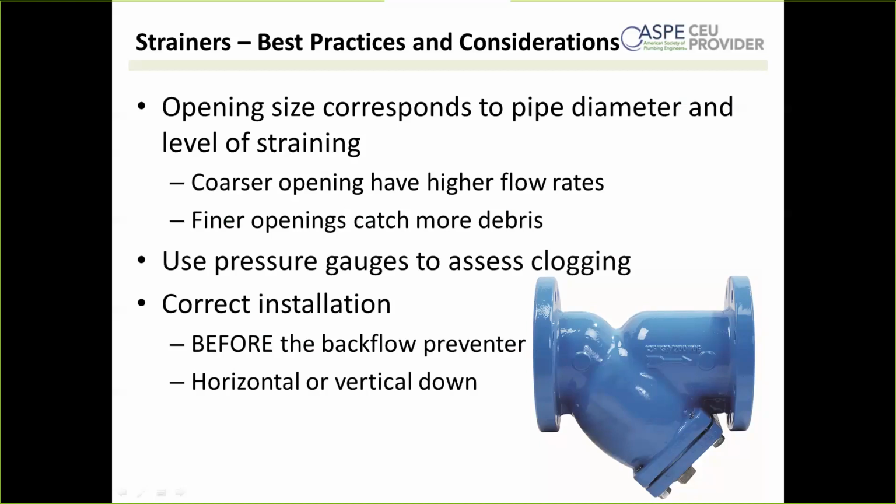I'd also like to note with that a Y strainer, such as this one on the screen, it needs to be installed with the drop leg, this portion sticking out, pointing down. Again, this puts gravity on your side, so when you go to clean it out, the debris has fallen down by the access cover, so it won't fall back into the system and just foul it up again.